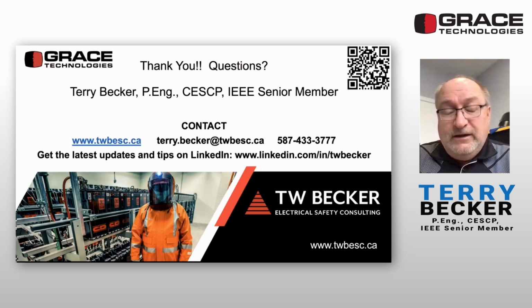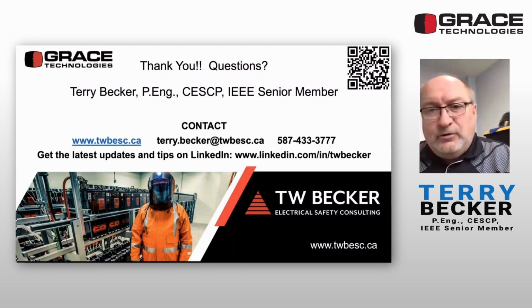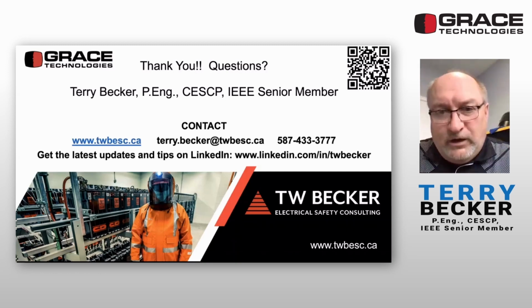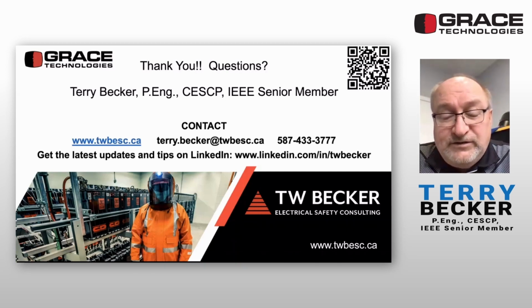I encourage you to read Annex R in 70E, but temper what you read, because for capacitors, shock is different, arc flash is different, and blast is different. We have to keep arc blast pressure for capacitors separate from AC and DC electrical, because it's not pressure, it's a shock wave, the way a capacitor will fail. So read Annex R, get clarity related to what's provided for capacitors, and then temper how you use that electrical hazard classification information going forward.